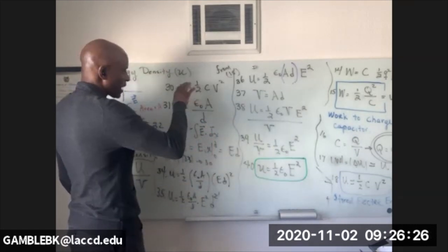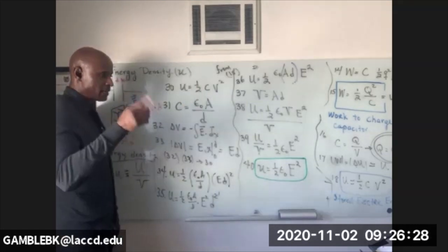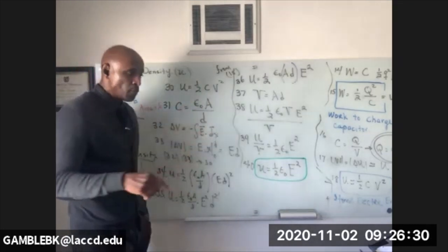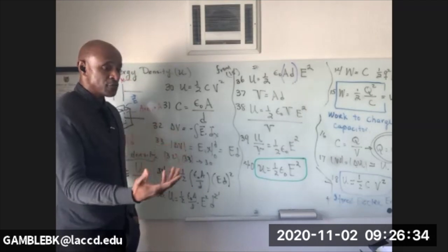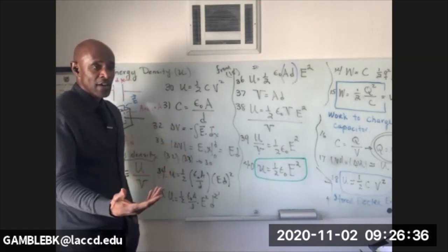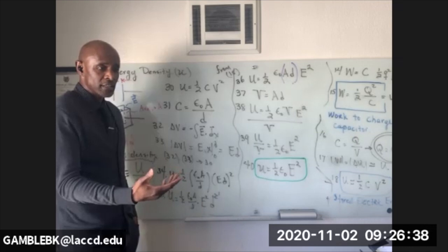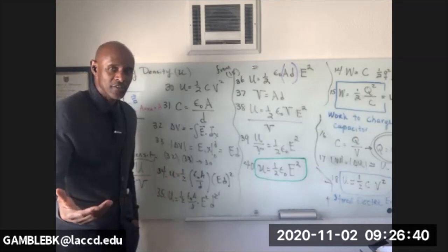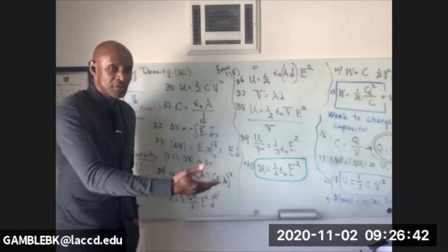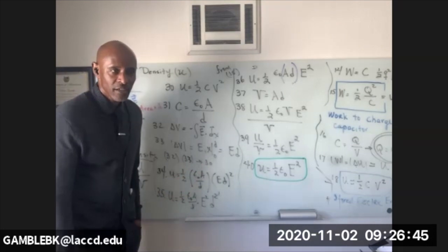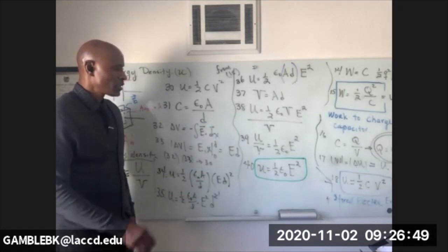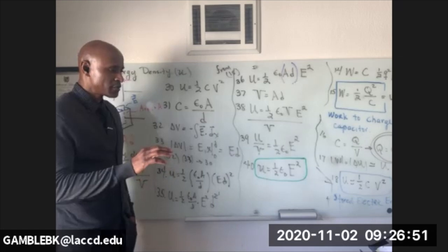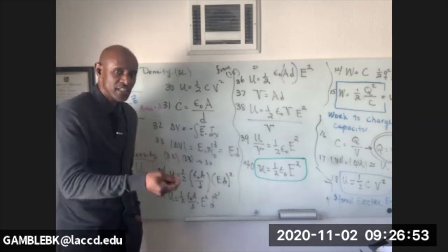Like here when I made the analogy of the same battery in different capacitors, what if you have the same capacitor in different batteries? Well, clearly you're going to have more energy stored, and that has nothing to do with the capacitor, but everything to do with how much energy you put in the first place. So it doesn't make sense to compare capacitors in terms of the actual amount of energy that's in the thing.